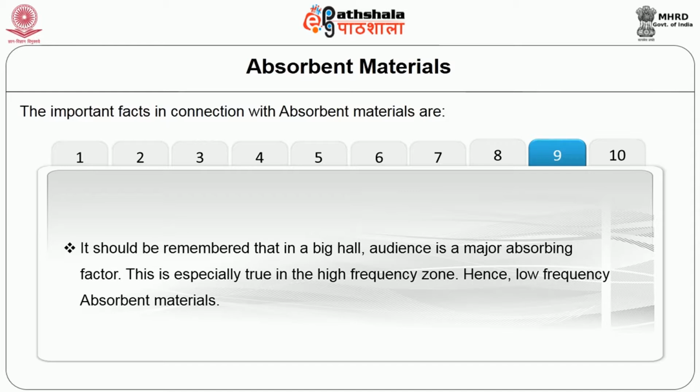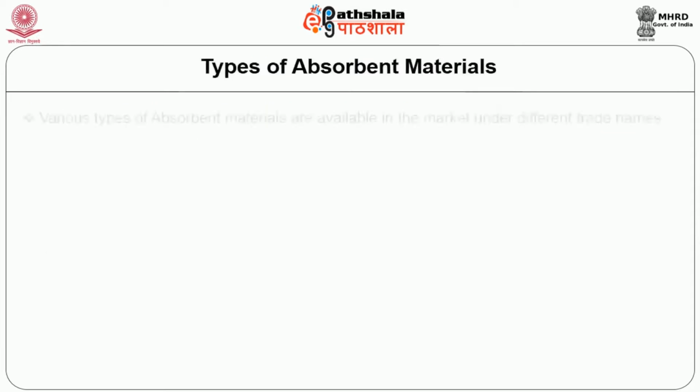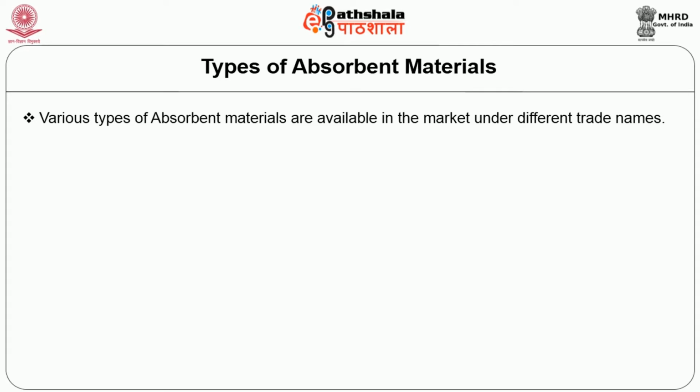It should be remembered that in a big hall, the audience is a major absorbing factor. This is especially true in the high frequency zone. Hence, low frequency absorbing materials should be provided to achieve optimum reverberation time over a wide range of frequencies of sound.